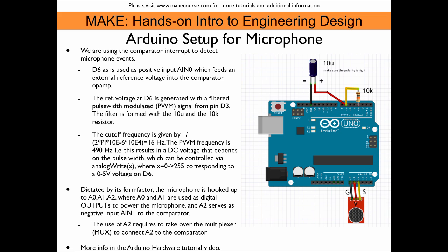Okay, now it's time to look at the Arduino setup. As I just said, we directly stick the breakout board of the microphone that has these 3 output pins. We stick that directly into the headers of the Arduino.